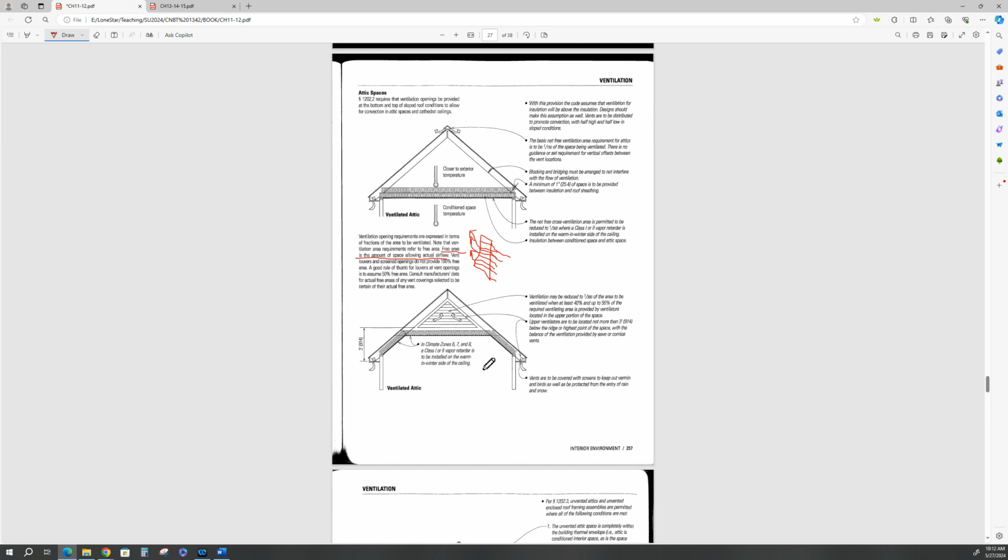A good rule of thumb is what again? I said a good rule of thumb is 50%. A good rule of thumb for louvers and vent openings is to assume 50% of the free area. If you did a triangular area here, the area is 1/2 the base times the height. If you remember your simple geometry, you can assume 50% of that. I would consult the manufacturer's data because these are also screened, and that will impede the amount of free airflow through the vent.